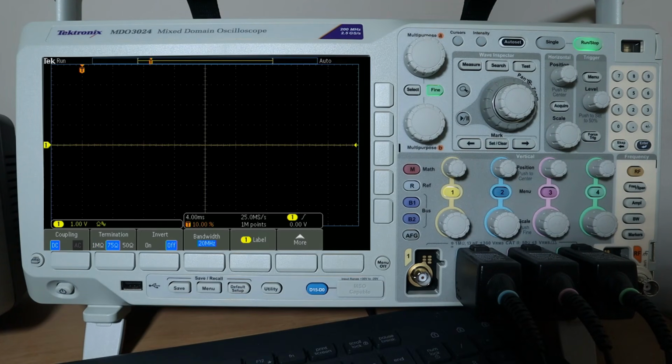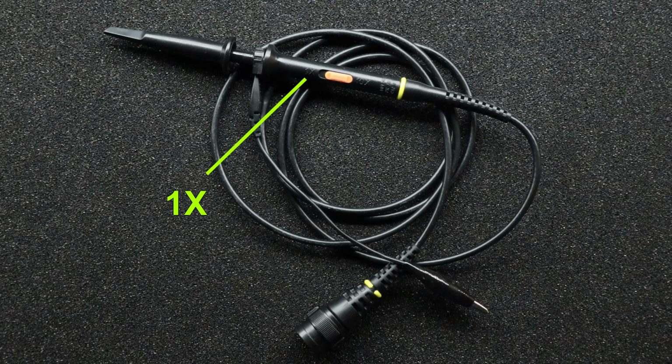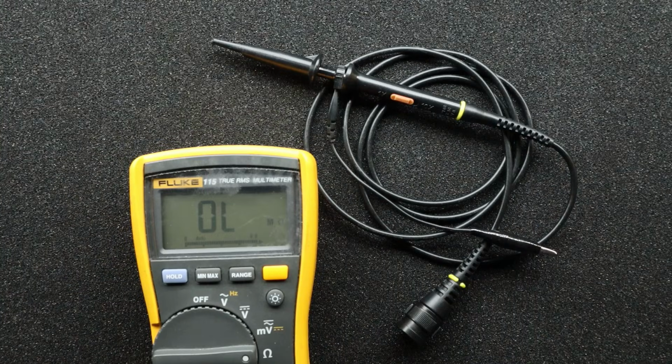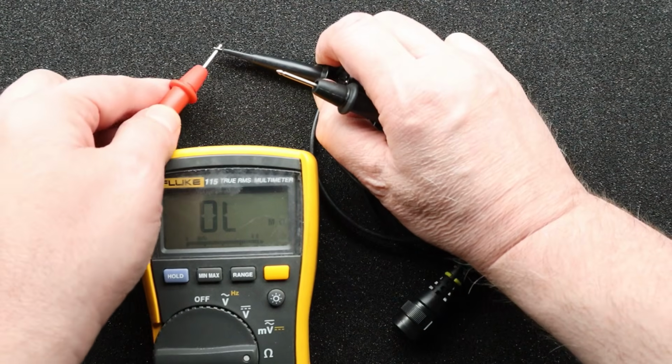You're most likely not going to have this option on lower-end scopes. I'll show some things you can do a little later if you don't have this option. We need to make sure there are no series resistances with our method of connecting the signal output to the scope input. You might consider connecting a switchable ×1 ×10 probe and setting it to the ×1 position. In the ×10 position, there will be a 9 megohm resistor added in series to the scope impedance, and using the ×1 option removes that resistance.